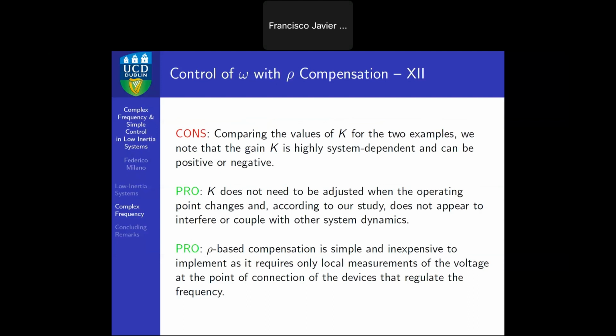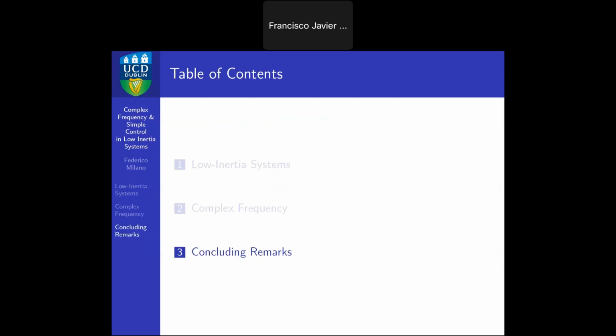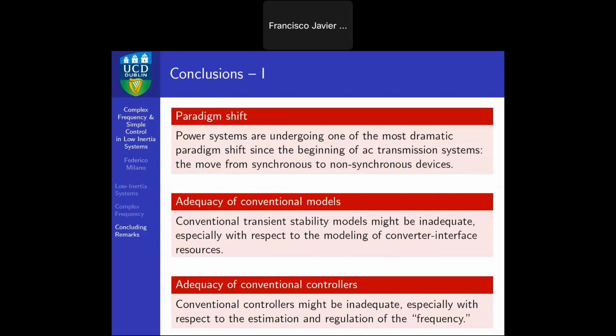And it does not make damage once you tune K properly. There is a wide range in which K can be set, and the control would be effective. If you want to find the best K, then yes, you need to look in this range and do many simulations. But it's pretty robust in the sense that it allows a kind of flexibility. It's not so sensitive.